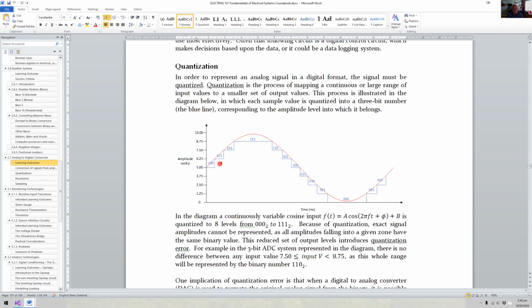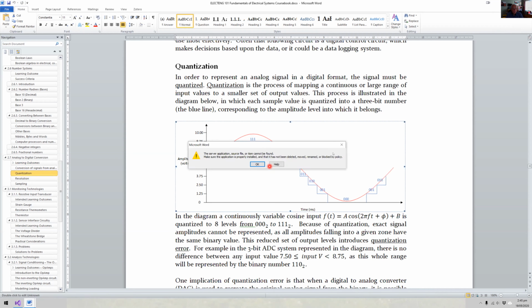So what we're saying here is that this ADC converter will convert between 0 and almost 10 volts. In fact, we will say that at 10 volts, 11 volts, 12 volts, it cannot go above 111. So it will limit that at that level. It will just cap it at that level of 111.